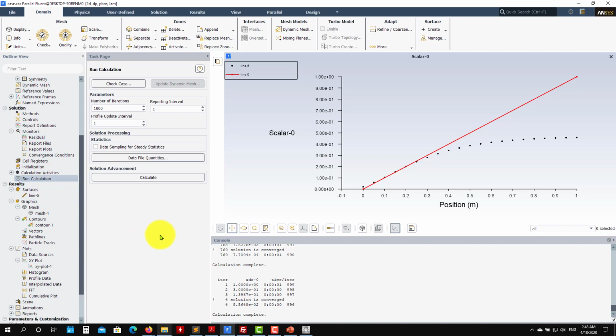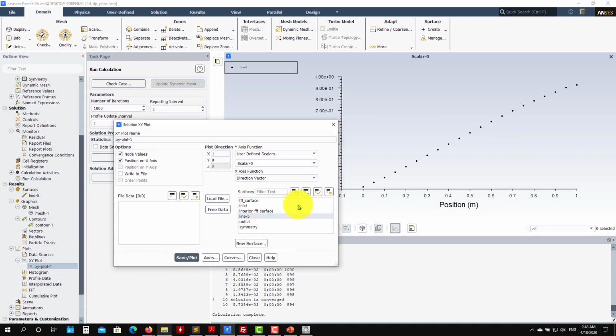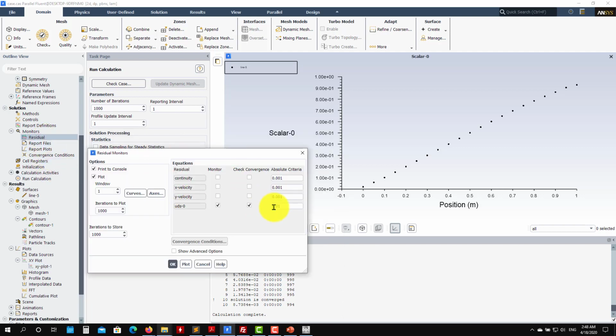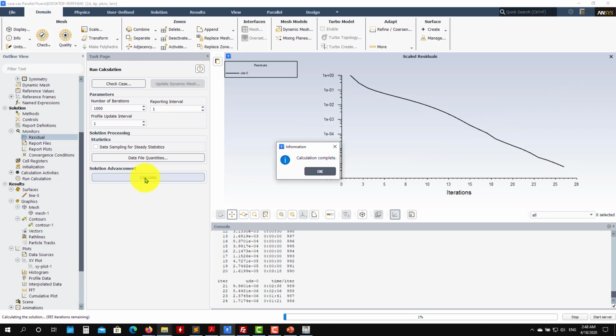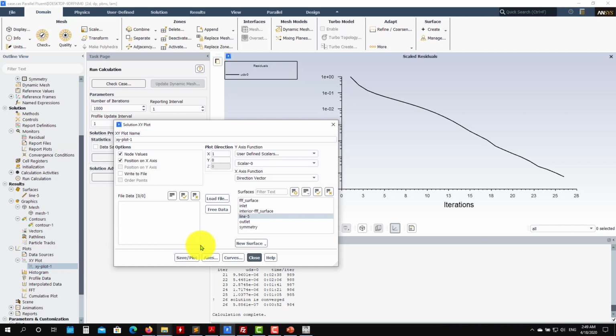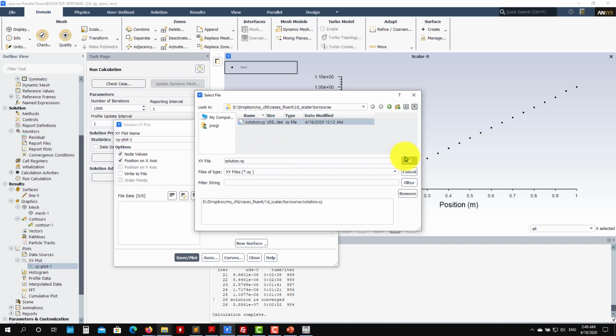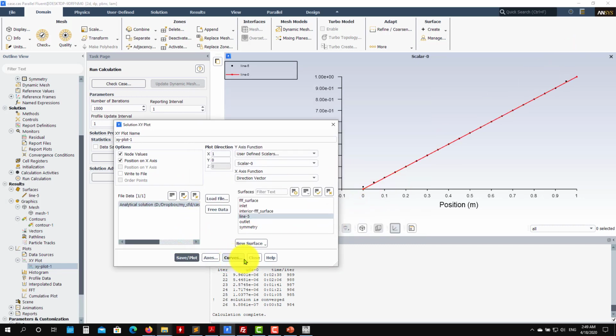I don't need to restart, I keep going from there. And voila, we reach a converged solution, and see that we still have a little bit of diffusion there, and we know that we go to 0.01. This is usually the standard criterion for a steady simulation. Okay, you can go to, let's say, this one. It will take more iterations to reach that one. And we plot, and not necessarily will you have a better solution, just a different convergence criterion. So very good agreement.